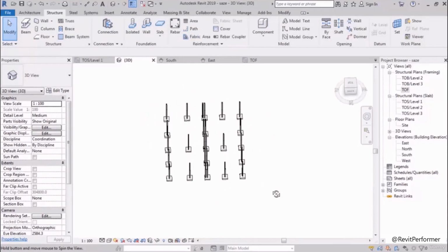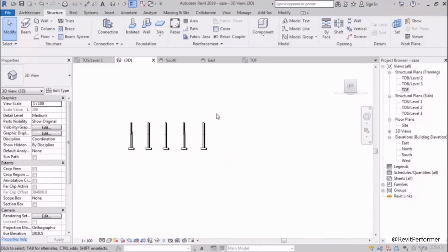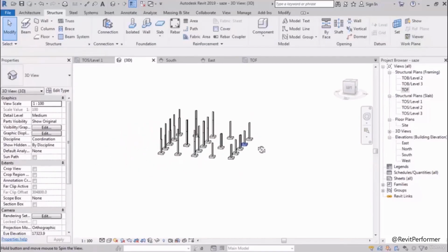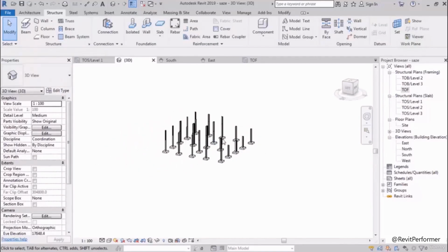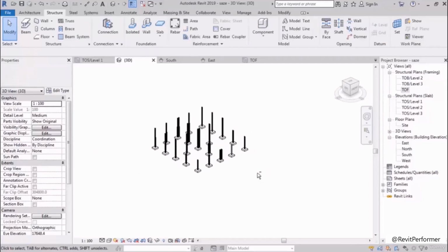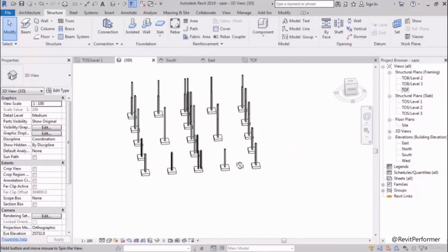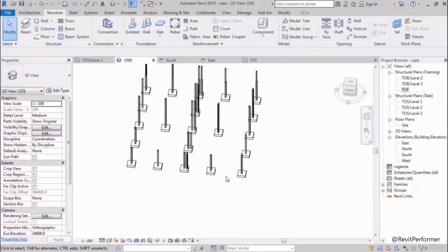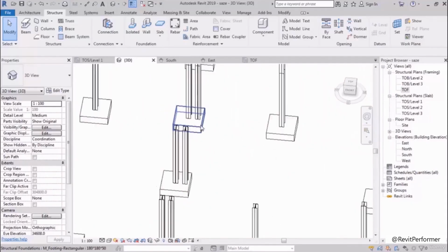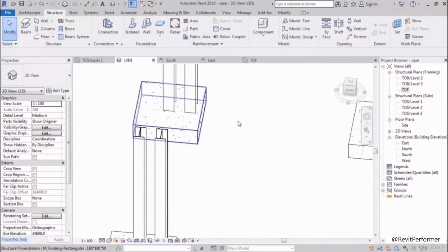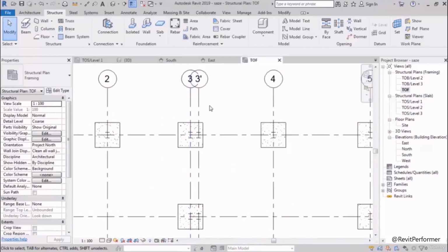Now, imagine that our project's next floor does not have this part. For example, it has a balcony. So you can draw it like this, right? Now, about this gap here, you might wonder why this foundation does not mirror. In these situations, you're going to have to fix it manually.